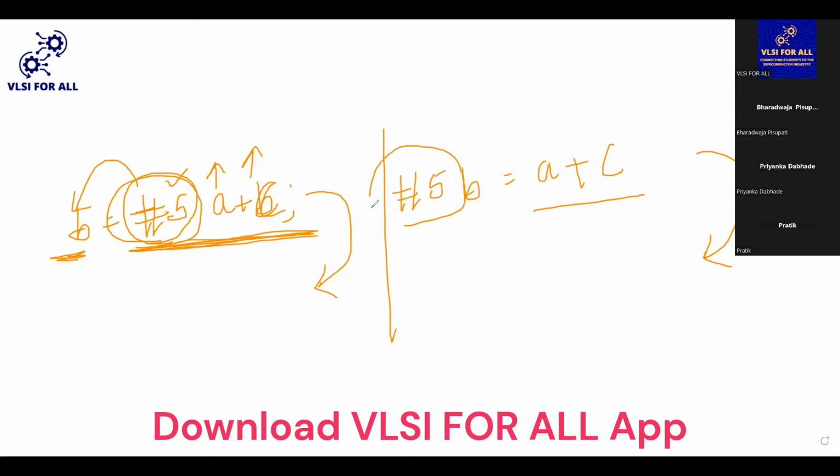Here this statement itself will start after the 5 nanoseconds. The statement will be waiting till the 5 nanoseconds, and after the 5 nanoseconds, whatever the values of A and C are there, those two values will be considered and the sum will be computed. They will be assigned to the value of B, and later it will go to the next statement. This is the major difference between the intra and the inter.